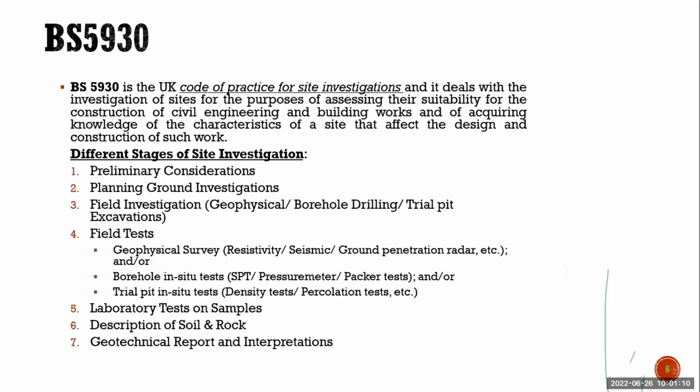That is called preliminary investigation. Detailed investigation, based on the preliminary investigation, we will do detailed investigation, especially for projects like dams and reservoirs. These kinds of projects are tunnel projects. We cannot do it in the beginning itself. We cannot say, okay, 100 boreholes, we do it everywhere. No, we cannot take the decision like this.